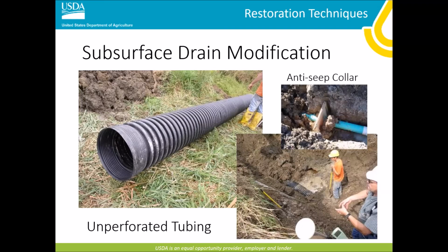One important construction aspect about doing solid tile is providing adequate compaction along this tube, and also providing an anti-seep collar along this tube to prevent any water from migrating along this drainage tile. It's unfortunate. You put it in thinking, okay, this is going to prevent my wetland from draining, but you have all the loose soils around that tile where that water will still want to try to flow. And like I highlighted there, the anti-seep collar, you can kind of see from the picture, is very important to have throughout our wetland situation to keep that water from wanting to migrate through it.